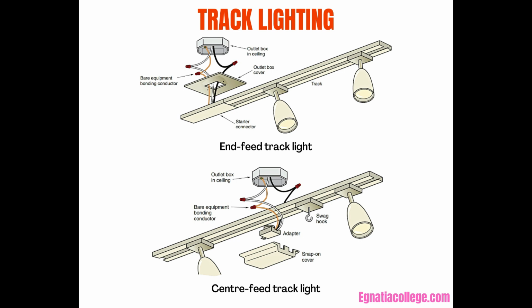Unlike recessed fixtures and individual ceiling fixtures that are fixed in place, track lighting offers flexibility because the actual lamp holders can be moved and relocated on the track as desired. Lamp holders, selected from hundreds of styles, are inserted into the extruded aluminum track at any point. The circuit conductors are in the track, and the plug-in connector on the lamp holder completes the connection. The track is generally fastened to the ceiling at the outlet box and with toggle bolts or screws. Various track lighting installations are shown in these figures.